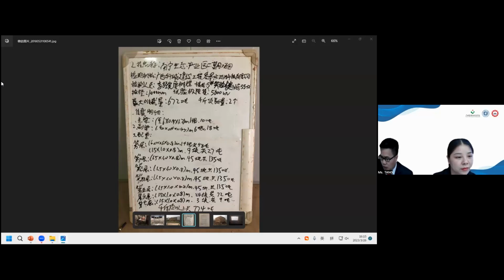If it is a pile which carries a bidirectional load, it should be the bidirectional test. But if it is a single directional load, it should be a single directional test. It depends on the force characteristics of the piles themselves.